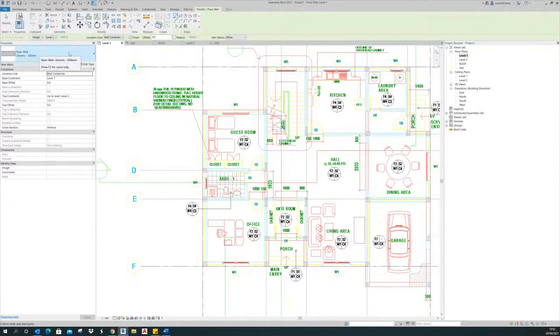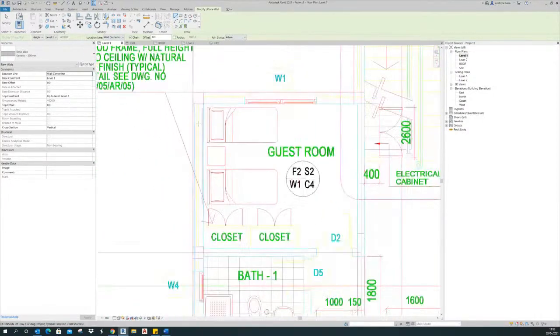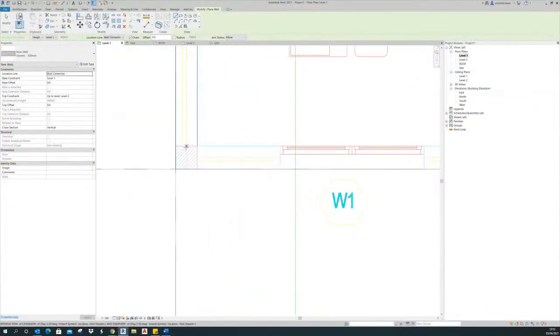Click the wall again, 200, and from level 1 up to level 3, automatically that becomes 4 meters. And this time, let's see if we have a center. Yeah, we have the center line. We use that center line. And then let's just create the wall from here.